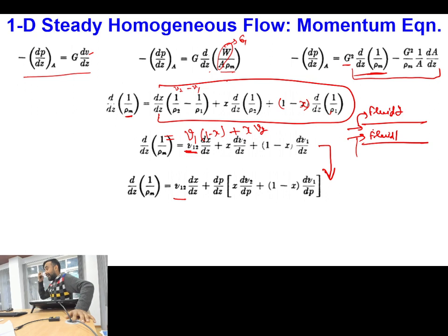Okay, so in an adiabatic situation, whatever the distribution of these flow rates will be giving a certain flow pattern, that flow pattern will remain almost the same within the pipeline. Okay, but there will be a change of flow pattern only if the fraction of the fluid is actually changing. Okay, so the fraction or amount of fluid is changing within the pipeline itself.